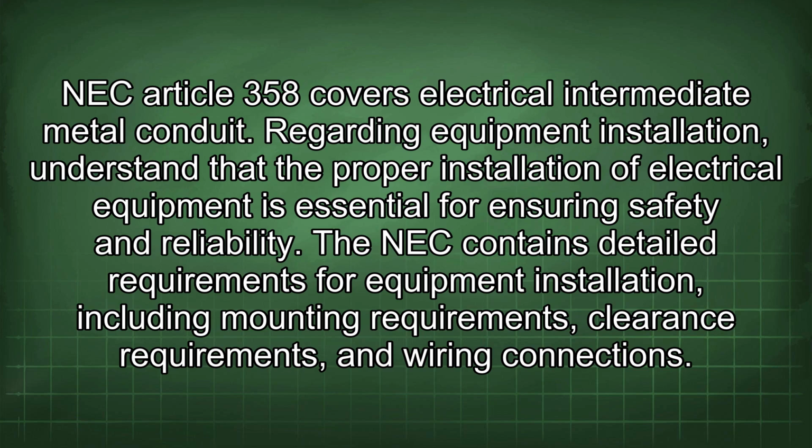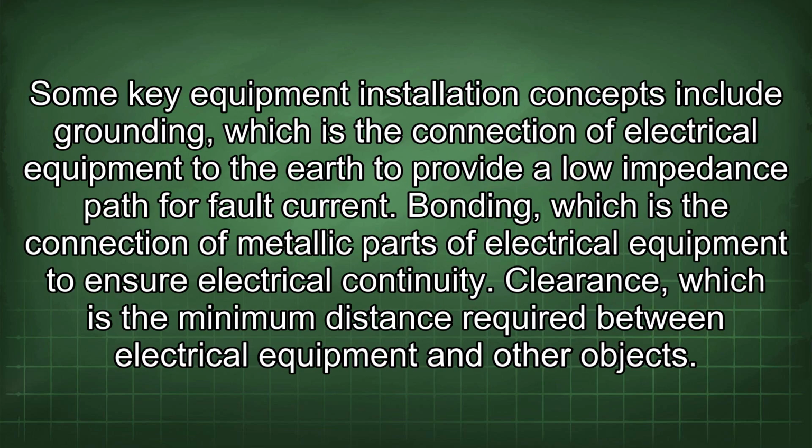Regarding equipment installation, understand that the proper installation of electrical equipment is essential for ensuring safety and reliability. The NEC contains detailed requirements for equipment installation, including mounting requirements, clearance requirements, and wiring connections. Some key equipment installation concepts include grounding, which is the connection of electrical equipment to the earth to provide a low impedance path for fault current.